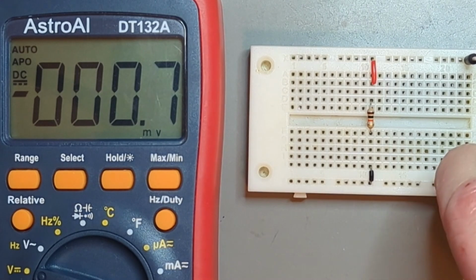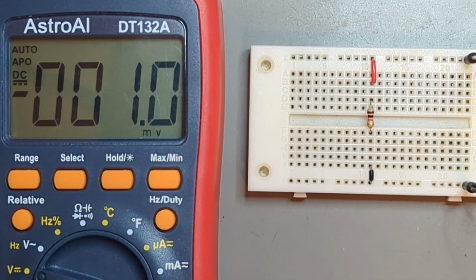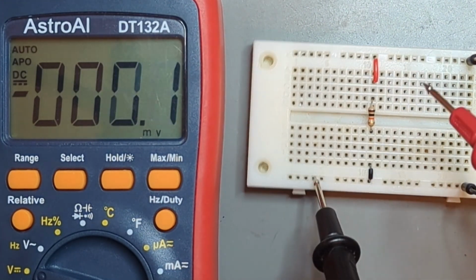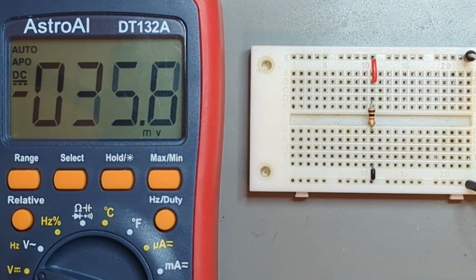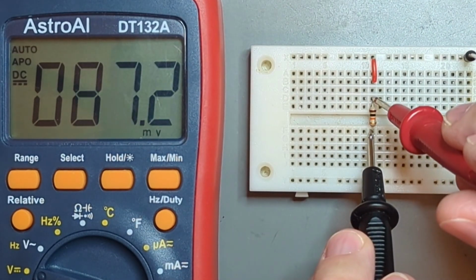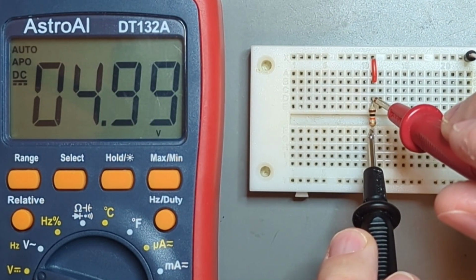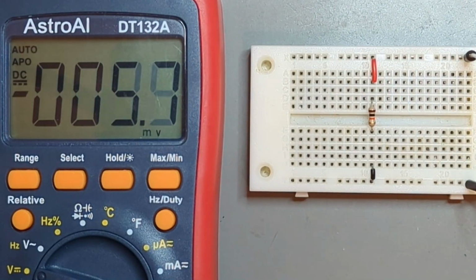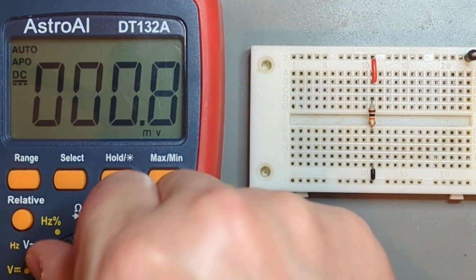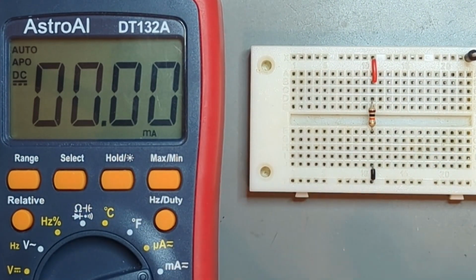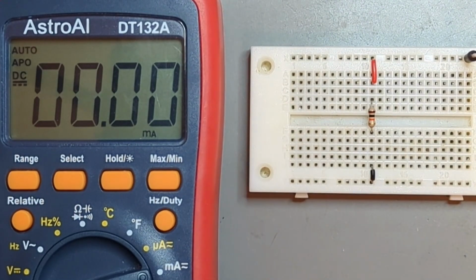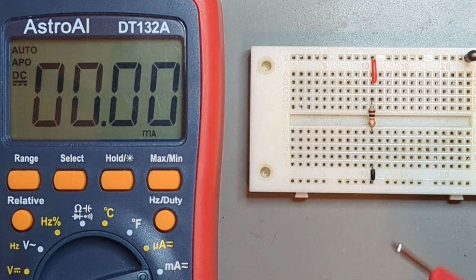Connecting up the supply, we can check the voltage. Remember that voltages are always measured between 2 points, and here I'm measuring directly across the resistor. 4.99 volts. Looks pretty good. Then we can switch over to current measurement mode, which turns my meter into a short circuit. To measure current, we put the meter in series with the load. I chose to put it on the ground side here, but it would have worked on either side.